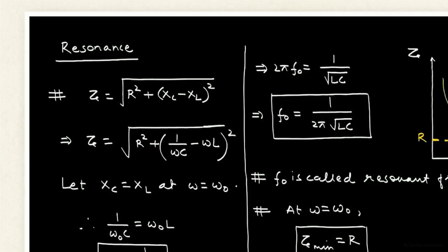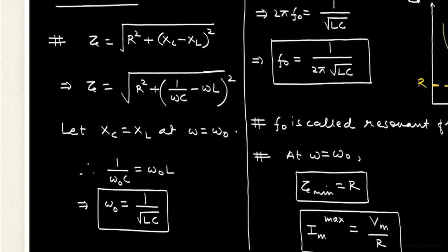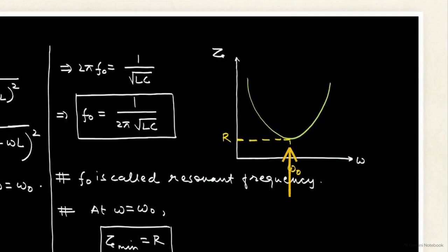This equation defines impedance, the total opposition to current. Expanding terms shows opposition is tied to frequency. The inductor and capacitor act in opposite ways. At omega naught, these reactive forces cancel out. The chart shows impedance hitting its absolute minimum, leaving only pure resistance, R.